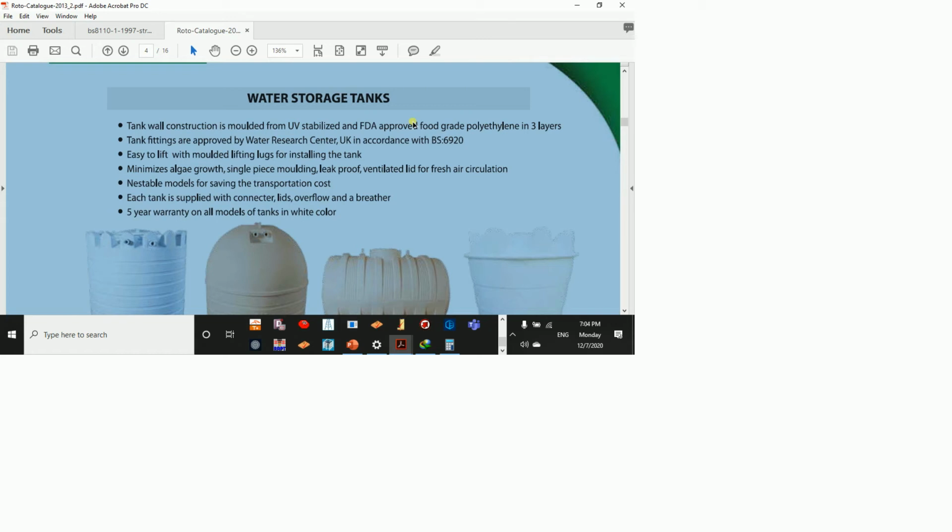if you are four persons holding a very heavy item, and one person leaves the place, the load is going to convert to the three. And if he returns, he is not going to carry the same loading as he used to, because a lot of loading has already been transferred to the other three. Right? The same scenario goes for a structure. If that column fails, other columns are now being stressed. Even if you put a steel column, it does not mean this steel column is taking the load, because the load path has already started to move.